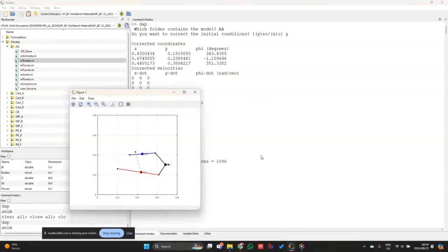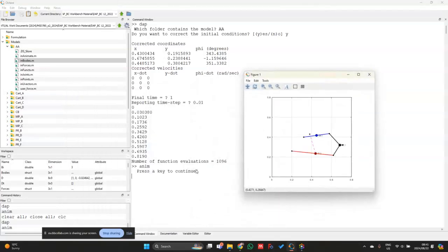what I'll actually see over here is that the wheel is now moving upwards. So the initial condition that I specified over there actually assumes that the tire is in contact at the start. So what it does is that spring or damper effect then pushes the wheel back up. So what I'm going to see on the y coordinates of body 2 when I plot that as well is that the wheel is in fact going to move up, and then I expect the dissipator forces to once again plateau or constant the y coordinate out. So I think it's just still running in the background. Yeah, so we'll just wait for that to finish and perhaps move this over here.